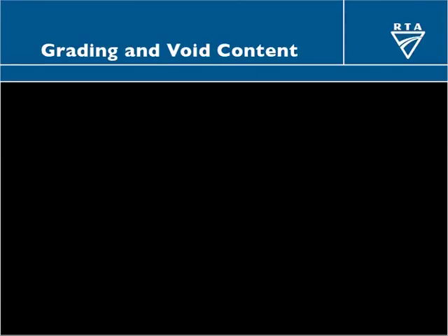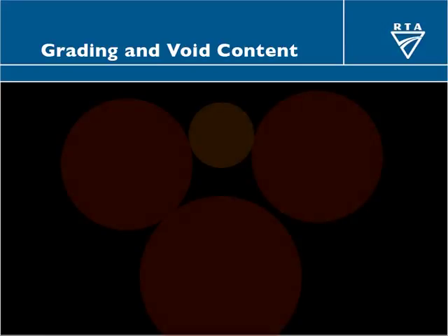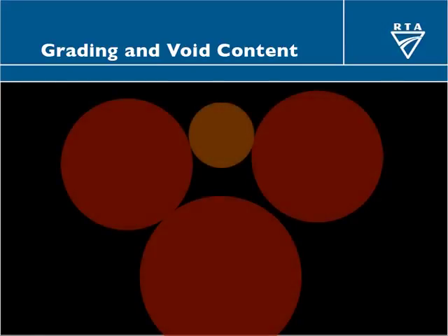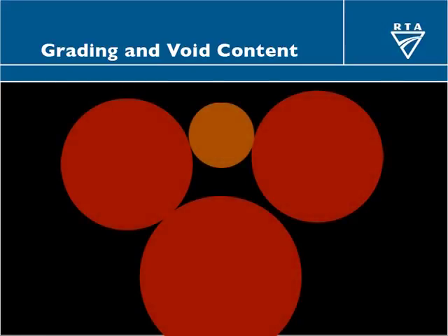Now, I talked a bit earlier about the effect of grading and the way particles are packed together. If we start off by imagining a group of sand particles such as this, there's a limit to how closely they can be packed together. I've shown this as fairly loosely packed, and obviously you can think of some ways of putting those back a bit more close together, but regardless of how you do it, there's still going to be some fairly large voids between the particles, which there is no way of filling.